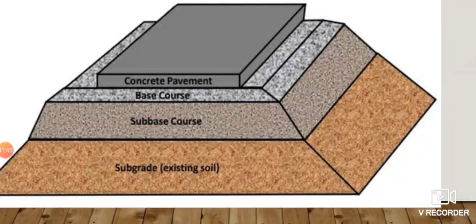And the second one is to serve as an effective drainage layer, to drain off the water entering into the pavement layer, leading to longitudinal side drains, right? So these are the main two objectives of GSB, granular subbase. So this GSB cum drainage layer serves as an essential component of flexible highway pavements. That is most important, right? Because most of the highways fail because of improper drainage.